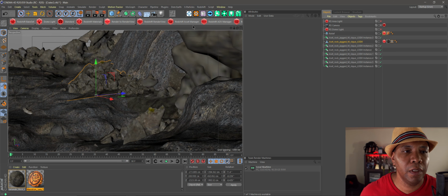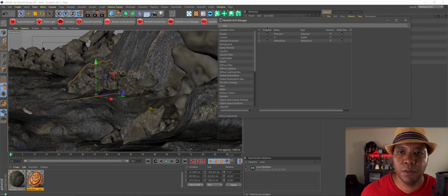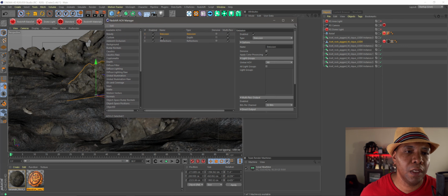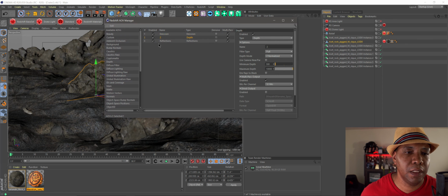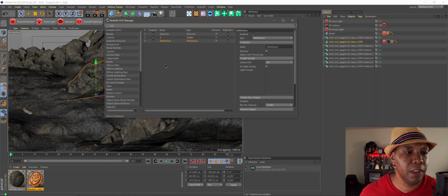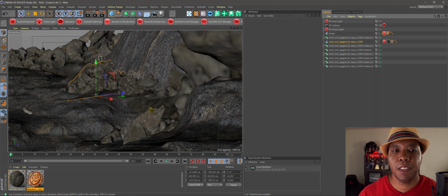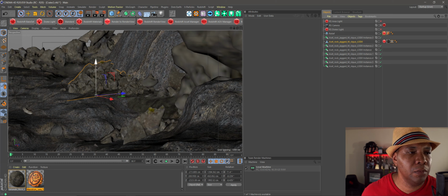And then if I go to my AOV manager, what I did was I brought in an emission tag, I brought in a depth of field pass, and just a little reflection there. I rendered those out, and then I composited everything in After Effects, which if you want my After Effects project, I can upload that as well to Gumroad. But yeah, I just used some glow filters in there and everything.